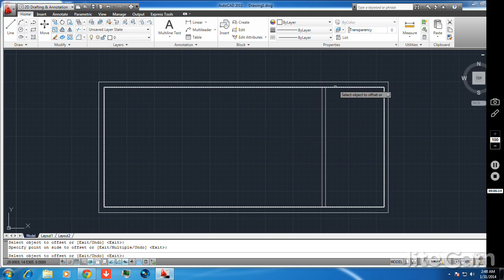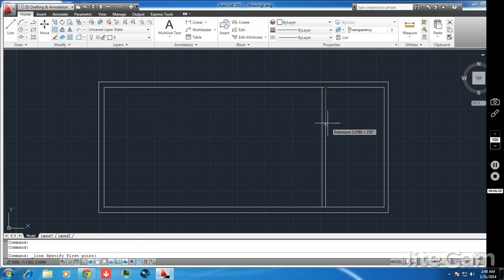This is the total portion, we cannot do anything in it. Now I take a line, a proper line, and go for it. Now again I offset by 0.3. Enter and specify the point. In this portion, where these lines are, in the 3D diagram this line gets removed, because it acts as a disturbance to create a 3D wall.